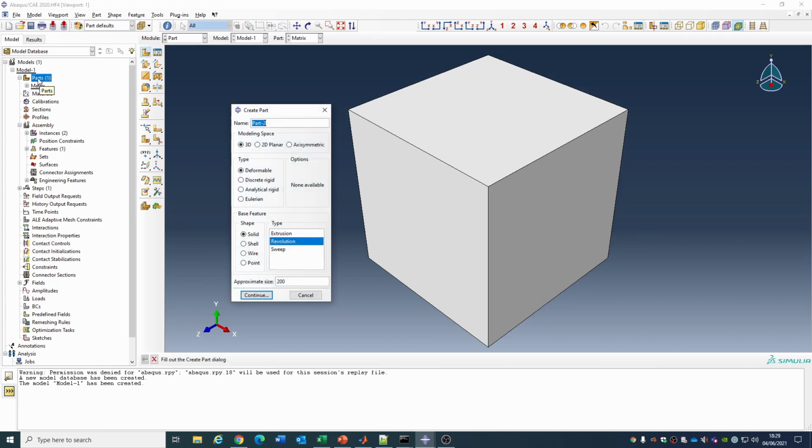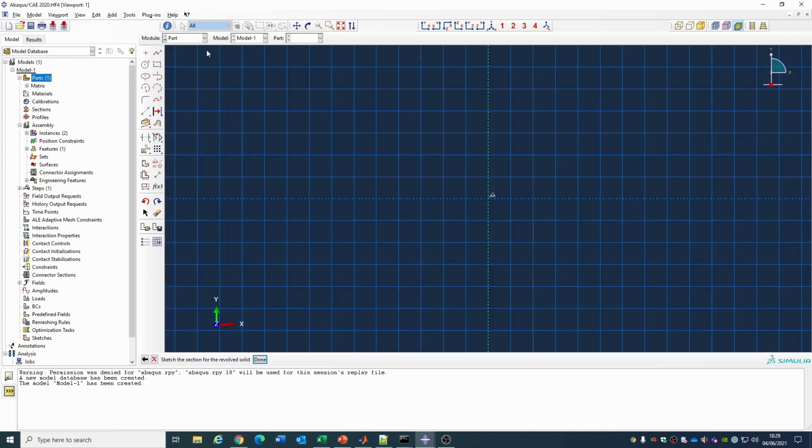To create the ellipse, we're going to have to do this differently. So let's look at the ellipsoid. It's going to be revolved. What I'm going to do here is create a new construction line, because I want the x-axis to be the axis of interest rather than the y-axis. I'll click here, so this point will be 20 on the x-axis and 0, and the y-axis could be 10, 0 and 10.